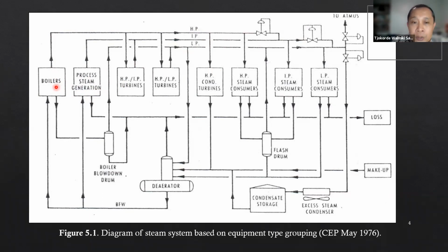Okay. It also doesn't make sense to produce steam at the HP condition when its usage is very small compared to the intermediate pressure and the low pressure. In that case, we have to have two separate boilers. One high pressure boiler, and the other one is a medium pressure or perhaps a low pressure boiler even.